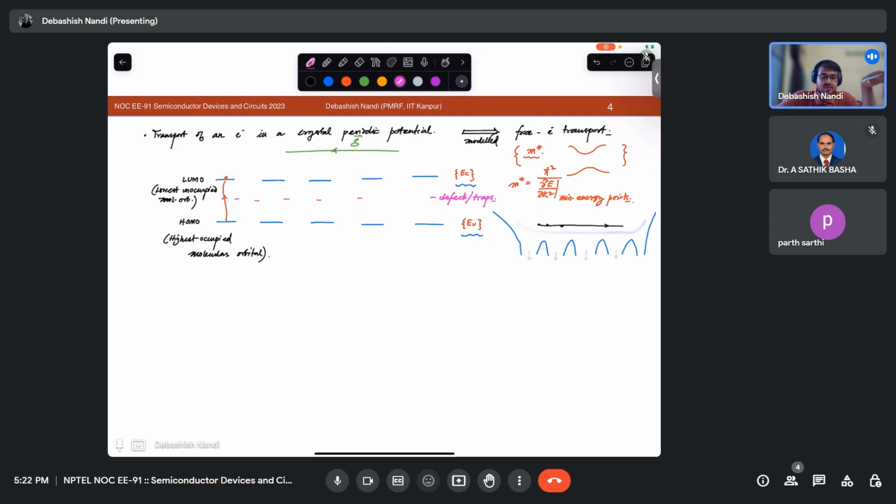How do you remove those defects? You have heard about fabrication processes like Czochralski, where you draw the silicon wafer, melt it and then draw the silicon wafer. So there are some purification steps, or costlier steps, to get the silicon that is used in the wafer for fabrication. That is almost very pure silicon. That fabrication requires first of all time, second money, and third multiple expertise.